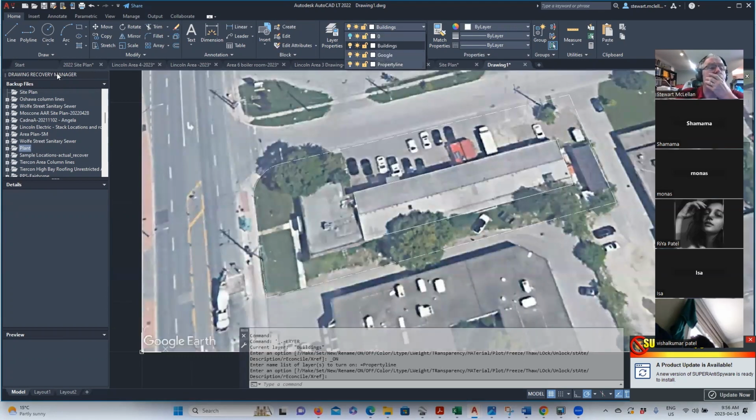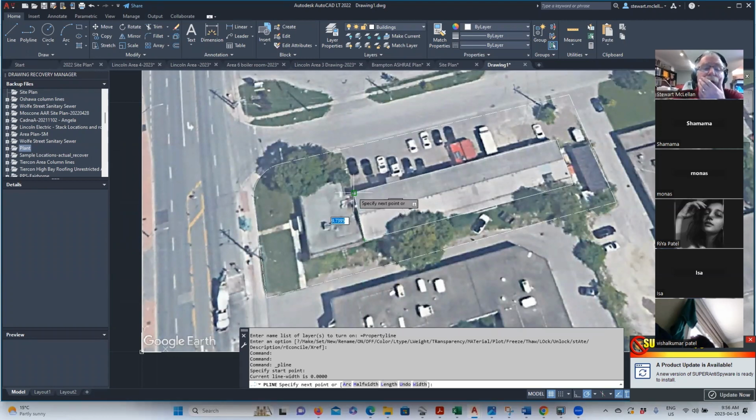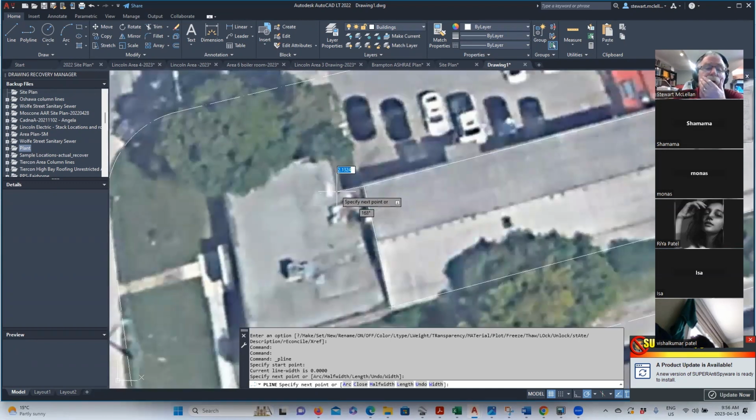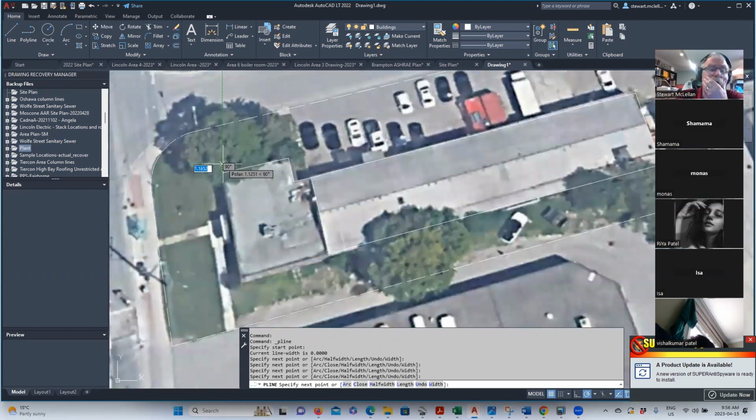All right. So now we're going to draw the second line, or the second building, and we want to use a different polyline so that they both get imported as separate shape files when you go to import them, right? So we're going to snap to this line here, this corner, and we're going to come up, snap to that corner, and then that building comes out to there. Okay, and it goes to here, to here, to here, and then I'm going to close it, right?